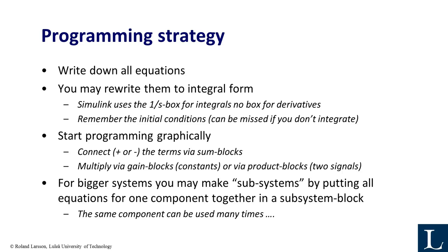When you are going to do some programming here and use Simulink, for example, I suggest that you do according to the following. You write down all the equations. You may rewrite them to integral form because then you can make use of Simulink's 1/s box.